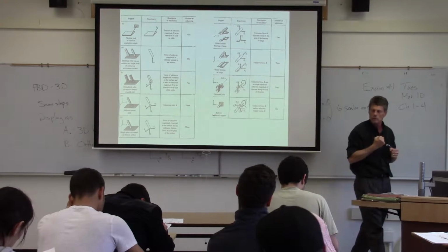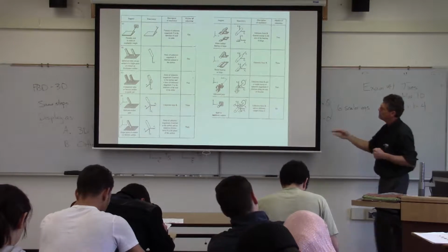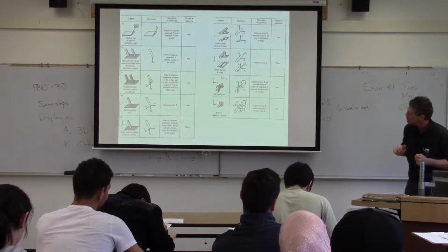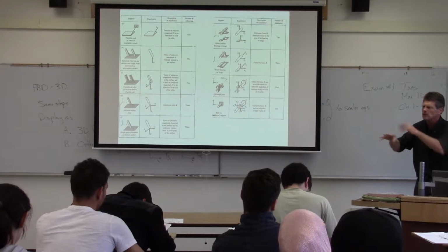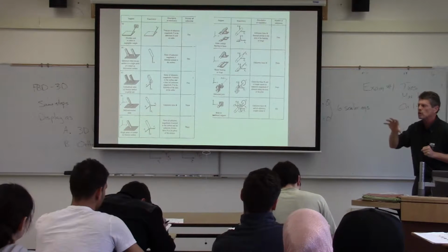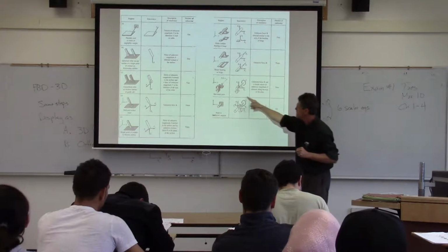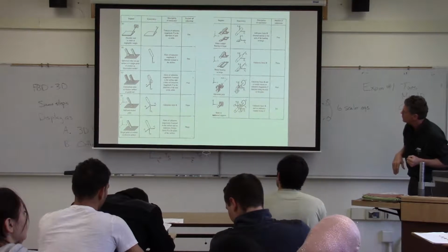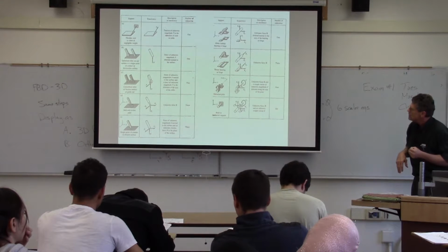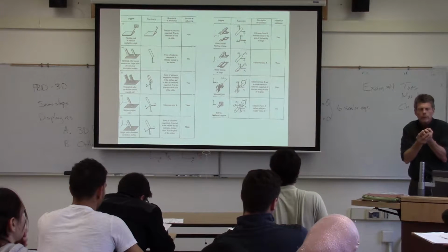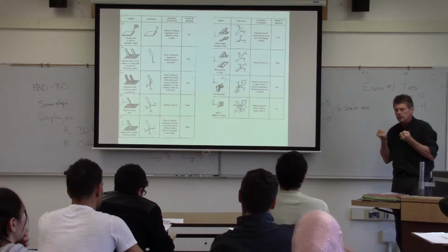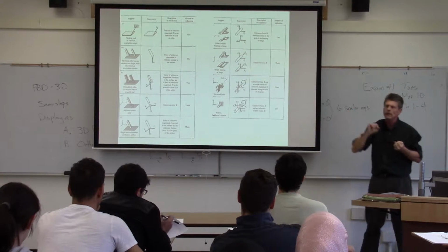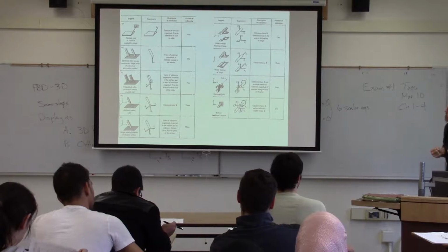We have 6 equations. So when we get to a problem like this, we better hope that the rest of the forces are known, or if we don't know them and it's connected to something else, then we need to go solve those, because by the time we get down to this particular point, we've got 6 unknowns there. We're going to have to start plugging through it. So that's an idea. Again, what we're doing in 3 dimensions is just simply removing these supports and substituting these forces, and they're going to come with their sets of unknowns.